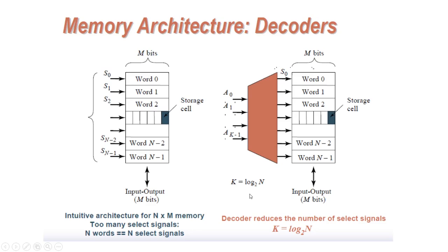Suppose you have n number of inputs here, the number of outputs of the decoder is 2 power n. Meaning, if you have only 3 lines, A0, A1, A2, I can have S0 to S7. That is, there can be 8 distinct address lines because of three binary address bits. So if it is 000, you'll be referring to S0. If it is 111, you are referring to S7.